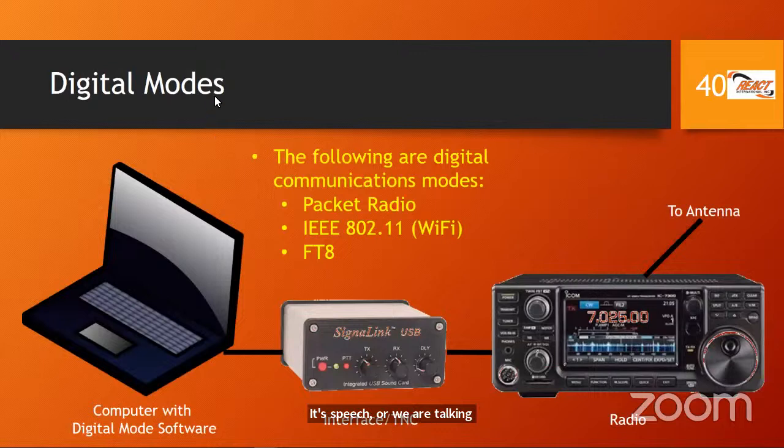As opposed to digital modes, we said it before, and this is our last slide, folks. We have a couple of exam questions in relation to digital modes, but remember we said anytime you hear digital modes, for our purposes for now, think of a computer connected to our radio. We have an interface here. Some radios interface directly to the computer. Some of them need an integrated device called a TNC or an interface to connect the computer to the radio. So digital modes, for now, simply means connecting a computer to the radio and letting the computer do the talking.